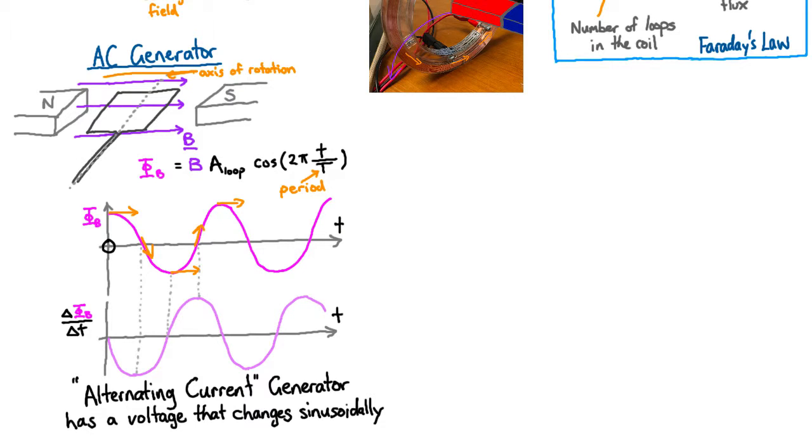So all the business end of the generator with the magnetic fields and the coils and whatnot is basically the same. But then once these wires come off here, we can construct clever devices that switch which wire these cords are connected to every half turn. And so what that's going to do is take our old alternating current and make it look like this.